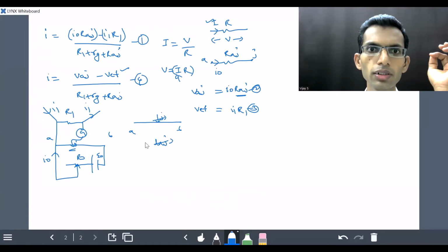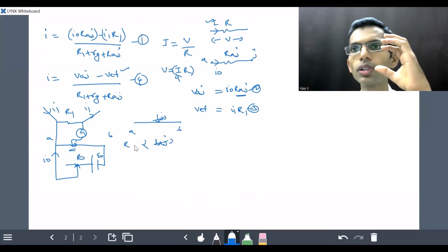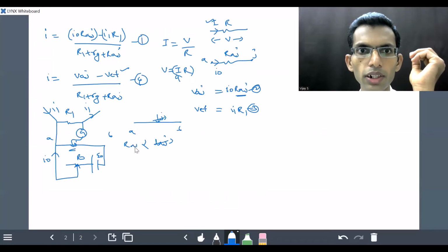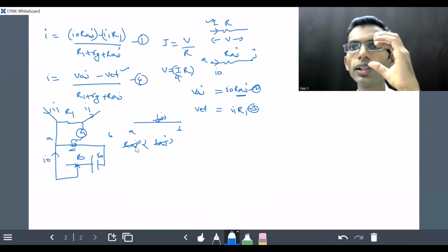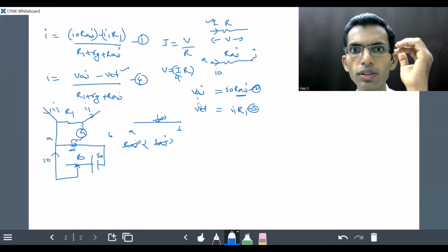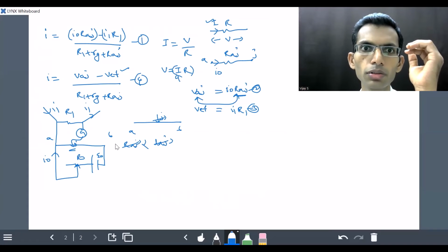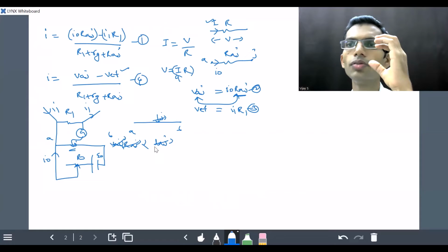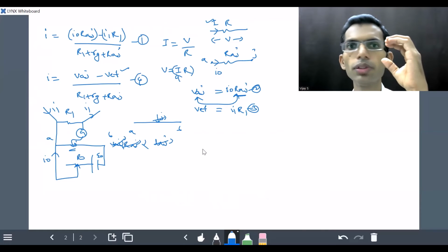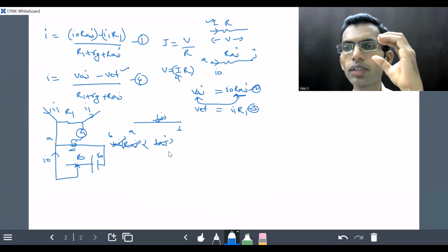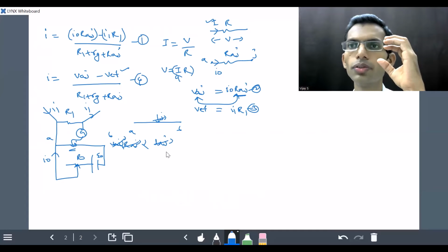When that varies, the resistance of the wire, which is proportional to the length of the wire, is also going to vary. When RAJ varies, you can see the VAJ, which is proportional to RAJ from equation 2, is also going to vary. So like this, when we move the moving contact J on the wire AB, as the length of the wire varies, the resistance RAJ and the potential difference VAJ are going to vary.